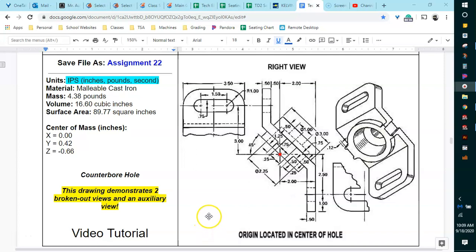In this video tutorial, we are going to be 3D modeling this object in SolidWorks. So the first thing I'm going to take note of is my location of my origin. Here I can see that the origin is located right here on the front of this angled piece. As far as the 3D view, it would be in the front of this circle, and it would be dead center.